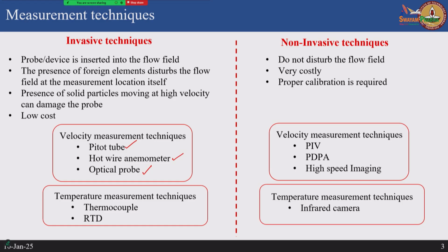Now, what about temperature measurement techniques? So, we use standard thermocouples, and these thermocouples have to be calibrated. That is very important, because the accuracy of the temperature data that you get depends on the accuracy of the thermocouples that you are using, and these thermocouples have to be calibrated with some industrial standard calibration units that are available, and sometimes people also use RTDs for very fast transient response and so on.